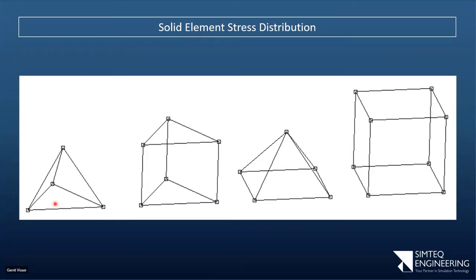There's no possibility for that face to have some kind of a distorted, curved section for a first order element. So if I have that kind of a deformed shape, I'll get this really weird gap starting to open up between the elements. I'll get a really, really strange stress distribution there. In practice, it's possible to connect them. It's just that it doesn't make sense.